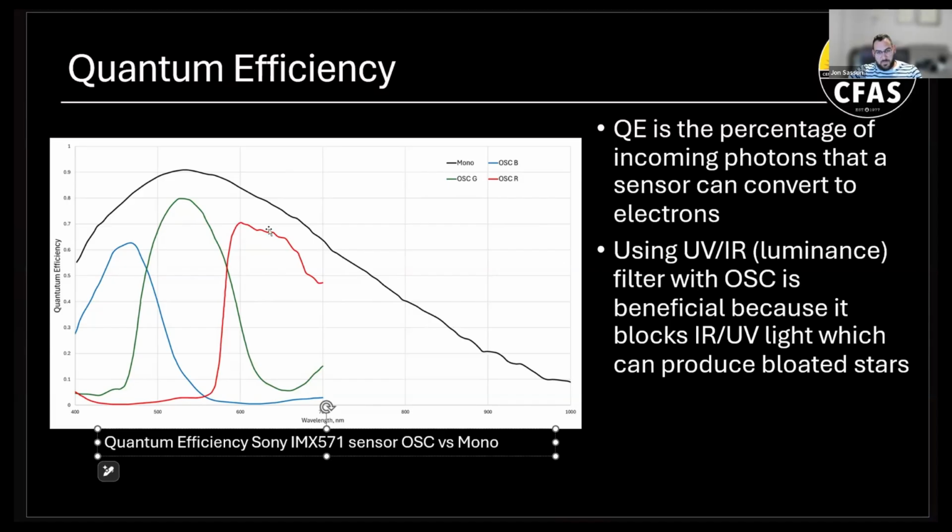If you look at the red at the wavelength you're getting from the red filters, your efficiency is about 15% or so lower than on the mono sensor, right? If I had the mono camera and added my own red filter in front of it, I'd still have a higher efficiency of light collecting. That's on top of the fact that you already have fewer pixels gathering red light.